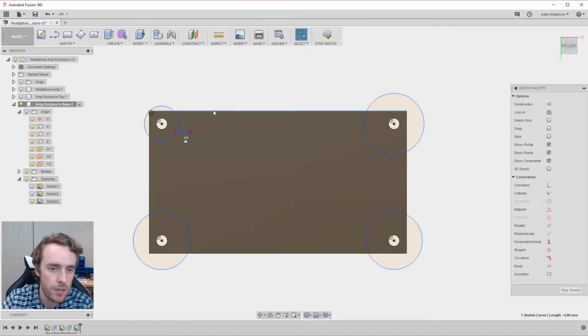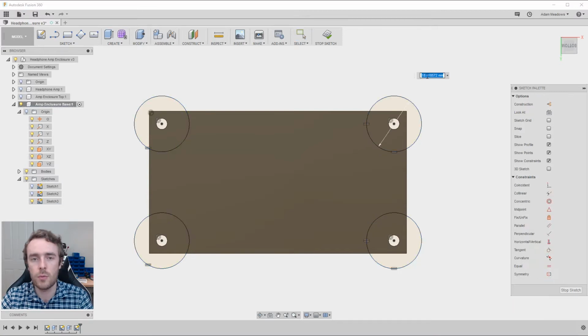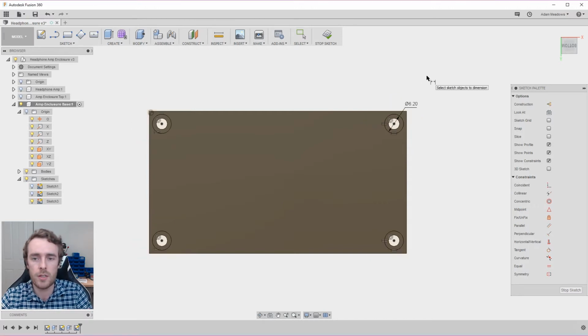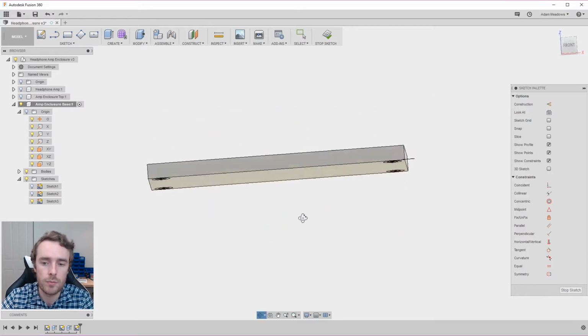we've actually created a constraint there that we don't want. Make these all equal. So we want the diameter to be just larger than the size of the head of an M3 button head or socket head screw. Button head's probably preferable because it's slightly lower profile, and so the head width is about 5.6 mil. So we're going to go with a 6.2 millimeter. In fact, let's just go 6 millimeter hole.